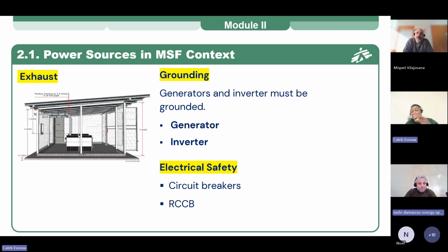Because even for the grounding rod, you cannot install the grounding rod like this. You have to give at least 1 meter or more to avoid this interference that we are talking about. So you mean maybe some current will go from our generator to the city power?